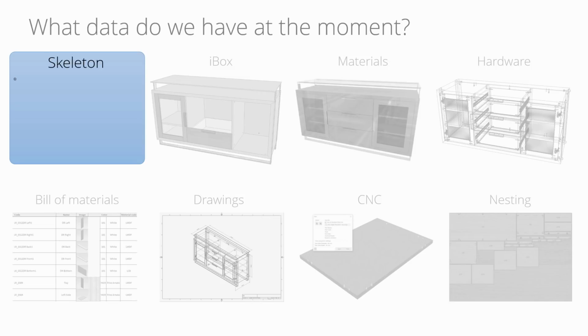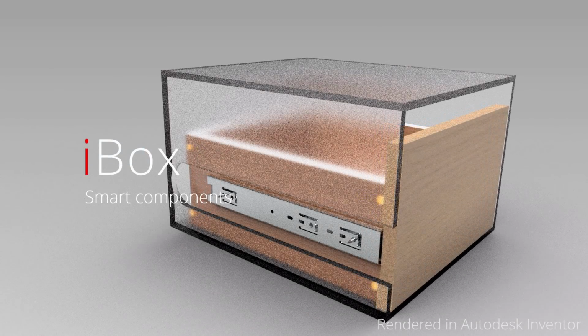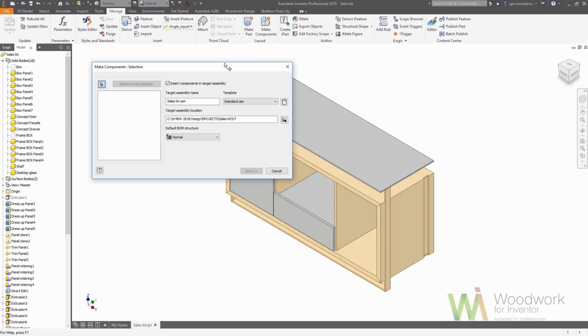So, what data do we have so far? We have a furniture concept, which is parametrically driven. We define the panels, and as well we define the place for iBoxes, which would be a drawer in this case. Now let's see what can be done with those drawers. Because drawers are more or less the same, with only a few parameter changes, the width and the depth, we can define them in advance. And such components are called iBoxes in our terminology. So now that's how our model looks.